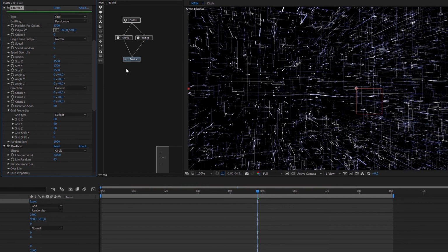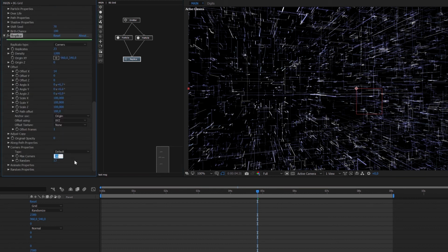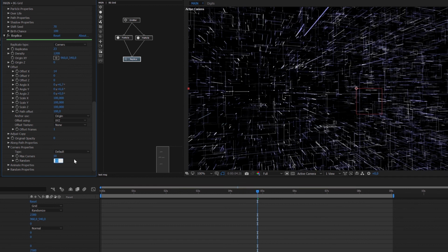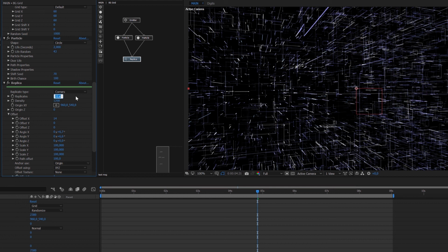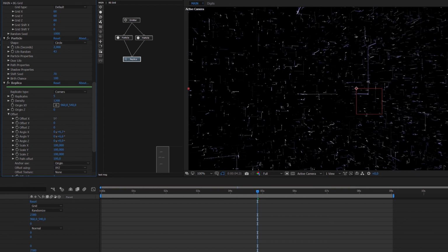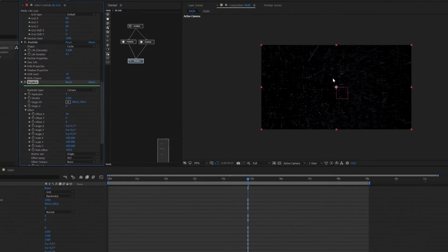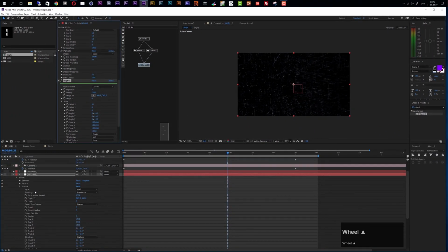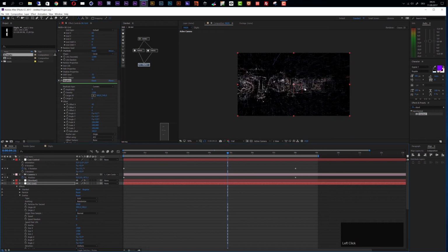Now I can change the replica here a little bit, so change the maximum corners to 10, change the randomness to 2 or 3. Now turn down the replicates to about 15 or even less, let's say 5. Offset something like, I don't know, 40 or whatever, to create such a grid. You know, it's not exactly the same as what I had, but you can play around with this. I just want to show you very quickly how to add this in the background. And now you see that you have this really complex setting.